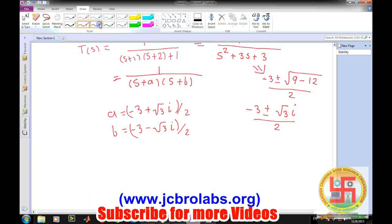If we try to plot the pole zero plot of this system, we will find that both the roots are lying on the left side of the S-plane. A will be here somewhere and B will be here somewhere, and this is the real axis and this is the j omega axis. This point will be nearly minus 1.5, and similarly we can easily find the other values. So both the roots are lying on the left side of the S-plane, and the system is stable.